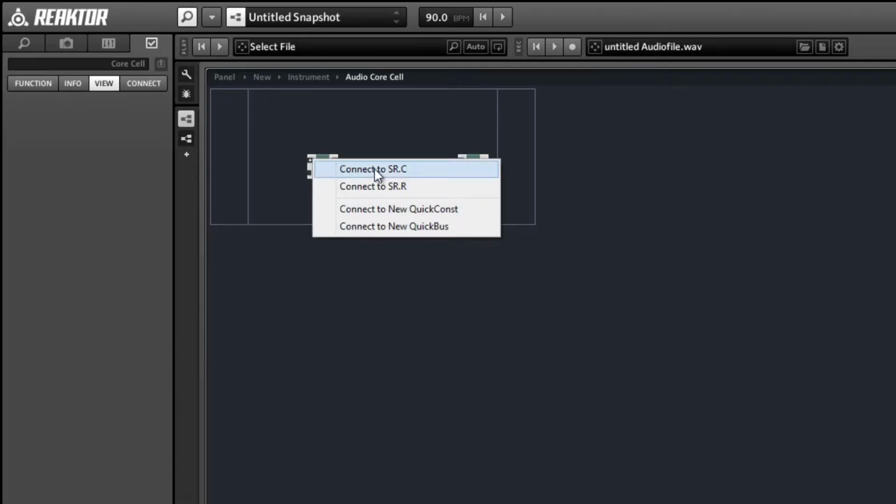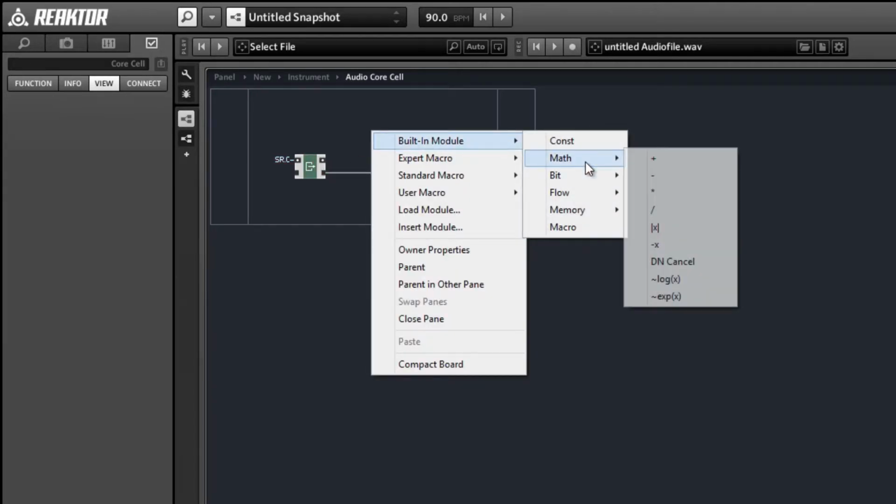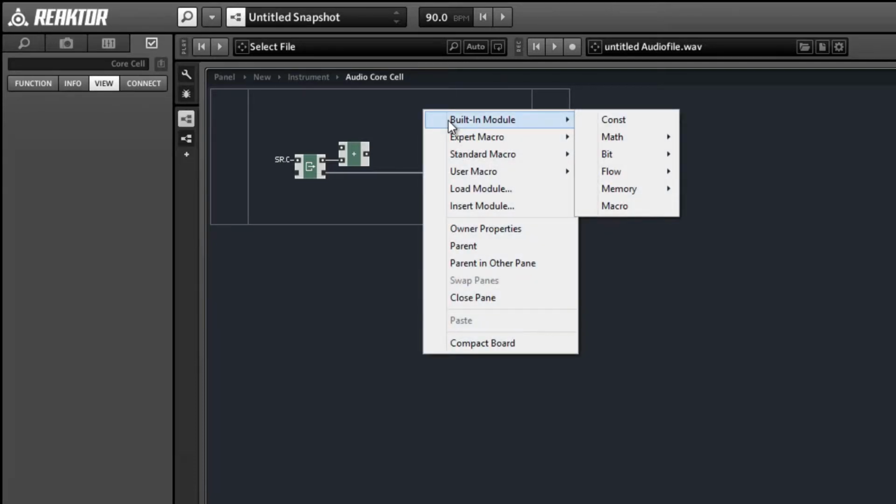And just like before, we're going to read out our value at every sample rate clock, and we're going to add a number to it. And what number we're adding every time is dependent on the frequency of the oscillator, so I'm going to leave that part blank for now. And we need to add one more thing, which is what separates a phase accumulator from a normal counter, and that is that we want to keep our value within a certain range.